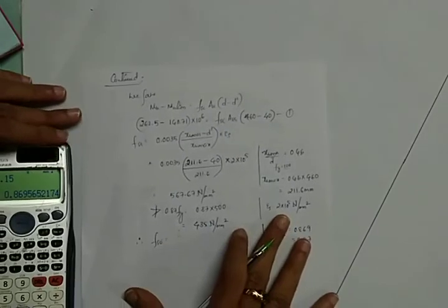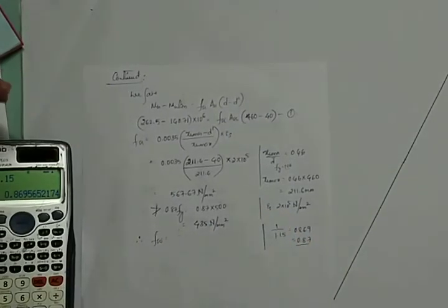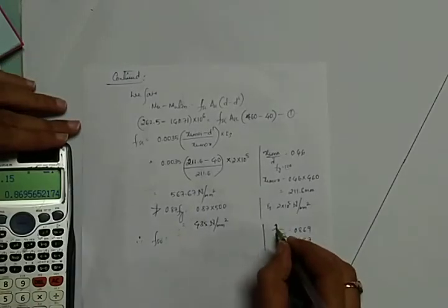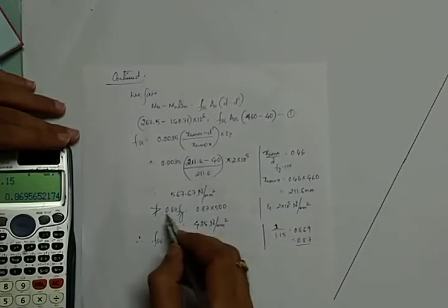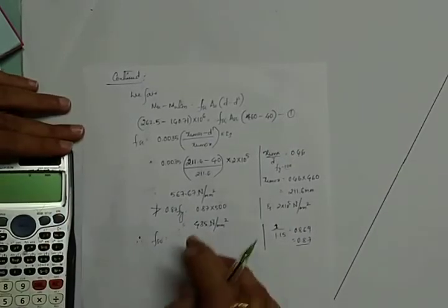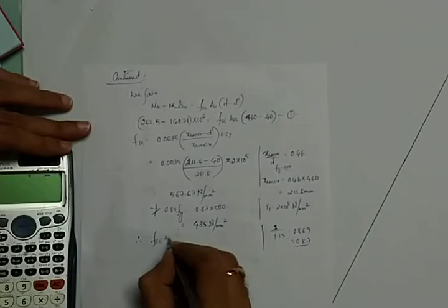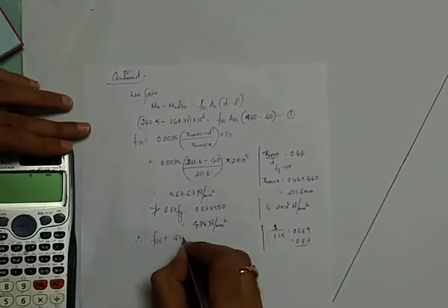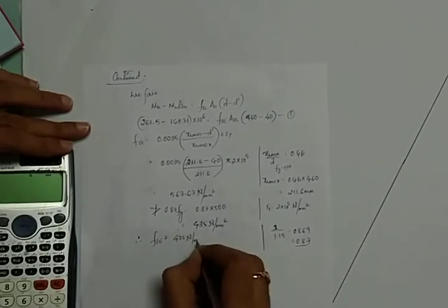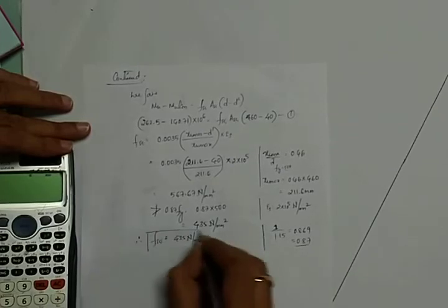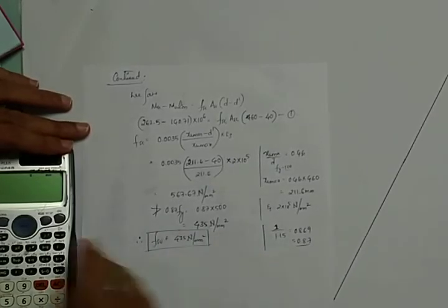In the class, while teaching the theory, I explained that for concrete we adopt a value of 1.5 as the factor of safety. For steel it is adopted as 1.15. So this is the explanation of this value. It should not be greater than this, so it has been limited to 435 Newton per mm square. Rounding off this value is also important.